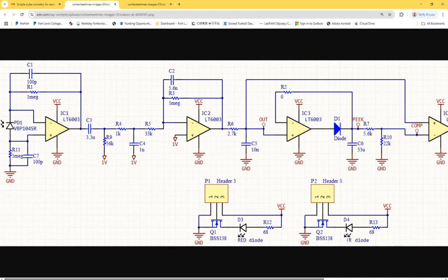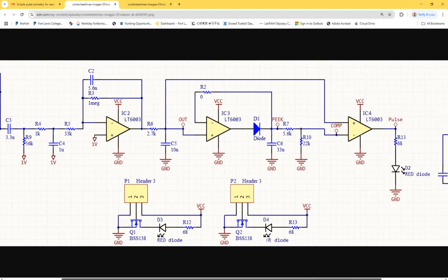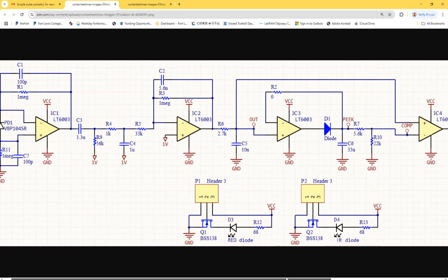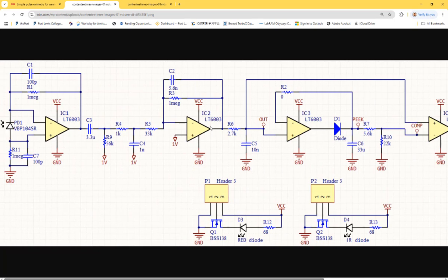Why do we want to see the spikes, right? It's actually a really simple circuit. Done. 1-2 stages. So what's the overall voltage gain? I'm asking for voltage gain. Just stop right here. DC voltage gain is only 1 mega divided by 33K.